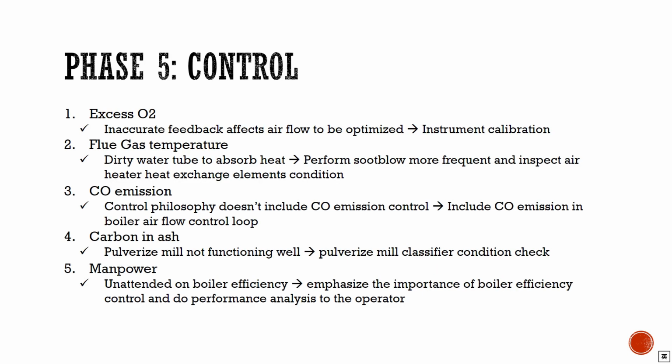So for excess O2, because it might be due to inaccurate instrumentation, we propose to send it for calibration, or we propose to have a more accurate instrument for measuring the excess O2, so that we have a better control.